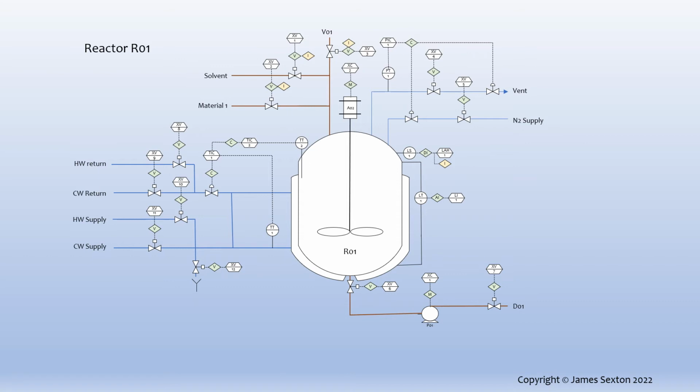Another type of basic control to consider is the sort of control that automates repeatable multiple actions for consistency and convenience. For example, we may want to set a jacket heating and cooling circuit to one of a number of possible configurations. For example, jacket temperature control, vessel temperature control, off or drain. The basic control here would set the regulatory control to cascade when necessary and sequence the hot and cold water supply valves as required. In ISA-88, this sort of repeatable group of commands and basic control of control modules is formally called a compound control module.